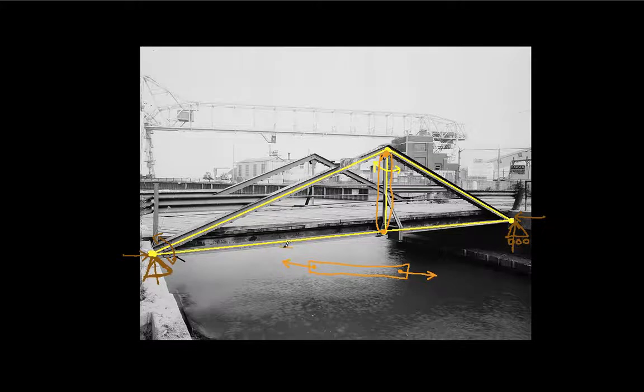So I can say that I might have a tension in a member TAB. At that side, I'll have that same tension in the opposite direction on this side. And we know that these forces have to act in the line of the member. Now, unlike a rope, where ropes can only pull on things, if you try to push on things with ropes, it doesn't work very well.